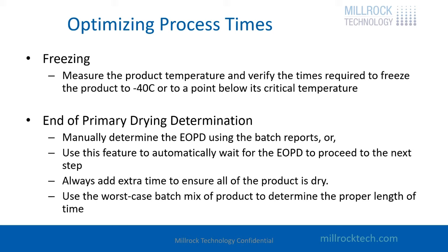By the way, anything that has an organic solvent in it, that organic solvent is going to come out first when you pull the vacuum on the system during primary drying. So you've got to be aware that that's going to happen immediately. And for the first 2 to 3 hours, that's what you're going to be getting out is the actual solvent.